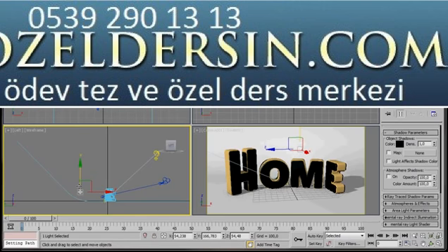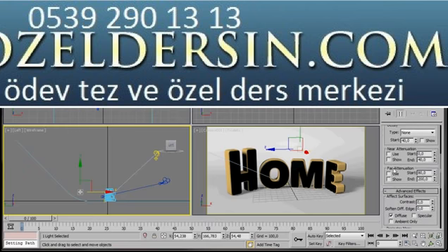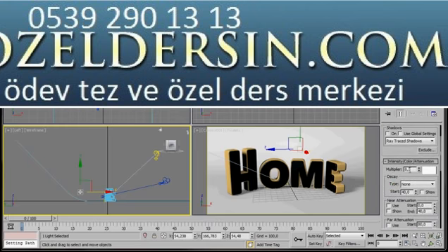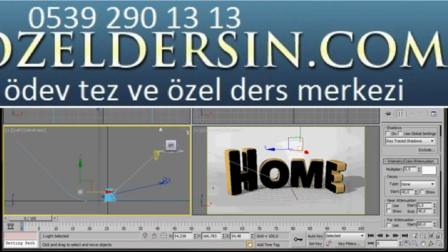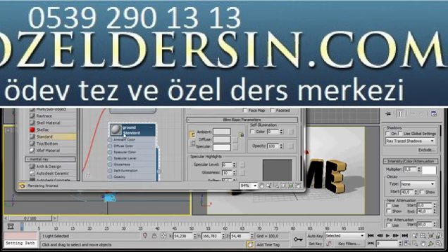We're going to boost the intensity of this Omni light, so we'll go over to the Modify panel. Make sure we're in the backlight. And then we're going to scroll up. And to Multiplier, we're going to change it to 0.5. As you can see now in the background, it's a bit bright. So we'll go over to the panel. And here in Shadows, click on the Exclude button, click on Ground, and the small arrow, and then now you can see it is in the other panel. We've just excluded that from the light. I think I'll lighten the background a bit more, so I'll open the Material Editor, click on the ground color, and then from the Diffuse Color slot, I'll just bring the dial down a bit more.